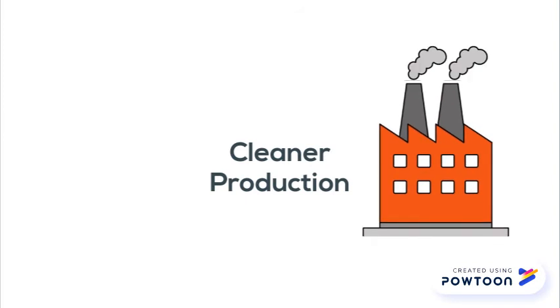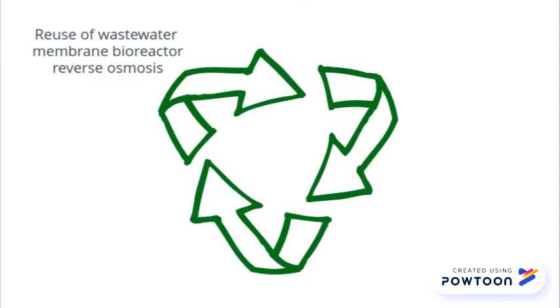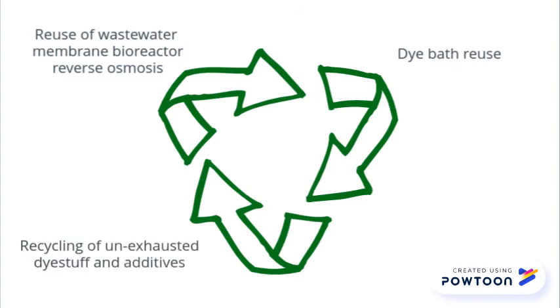Now, let's introduce some possible solutions for creating a more sustainable textile industry. We will go through the methods very briefly. There are many possibilities to recycle wastewater in the textile industry. It's easier to reuse the water from rinsing steps later in the process since less hazardous substances remain. When there are higher concentrations of chemicals, proper cleaning methods are needed. One applicable method is reverse osmosis, which can be used in the membrane bioreactor. Other recycling methods are dye bath reuse and recycling of unexhausted dye stuff and additives.